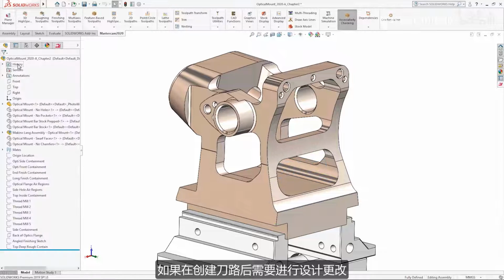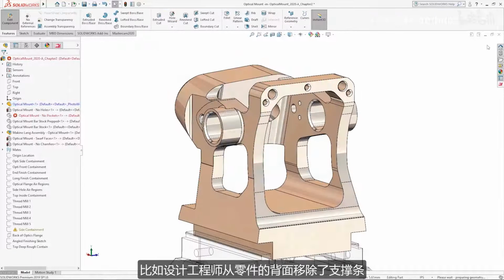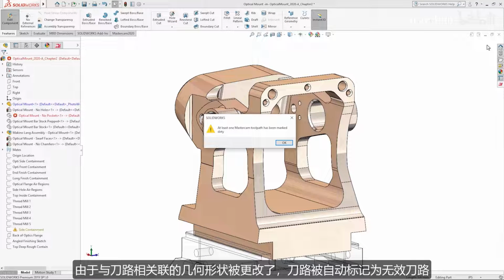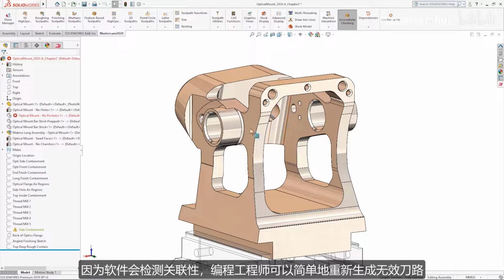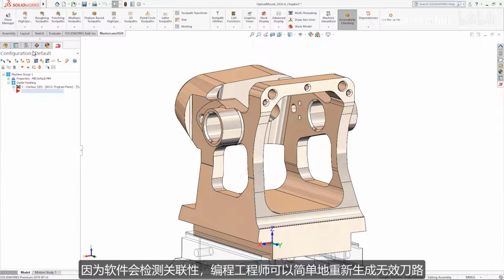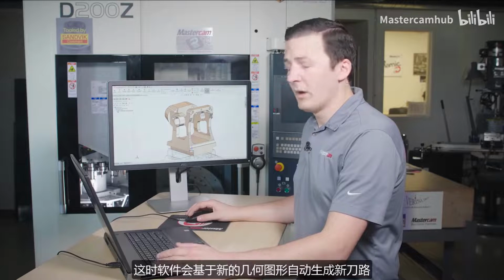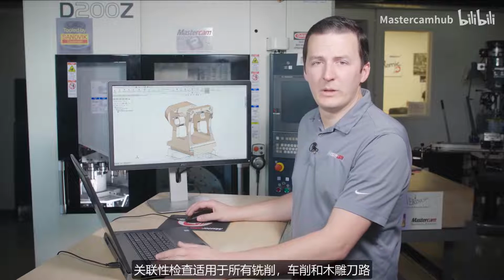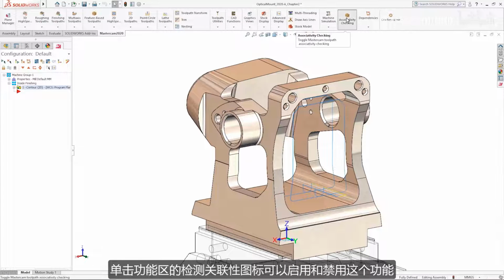If there was a design change after this toolpath was created, let's say the engineer removed the rib from the rear of the part, the toolpath would automatically be marked dirty since the geometry associated to the toolpath has changed. Thanks to associativity checking, the programmer can simply regenerate the dirty operations and the toolpaths will update to use the new geometry. Associativity checking works with all mill, lathe, and router toolpaths. It can be enabled and disabled from the ribbon by clicking on the associativity icon.